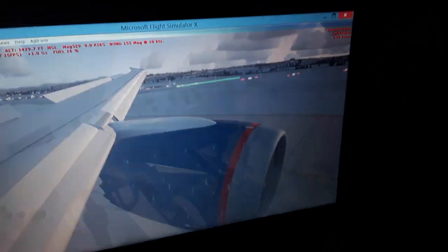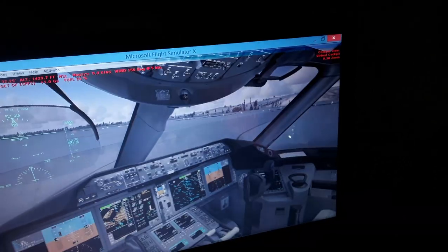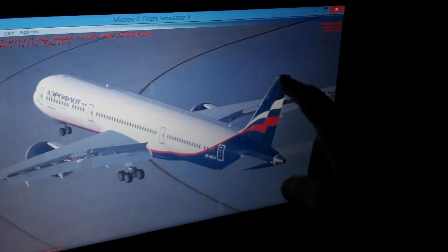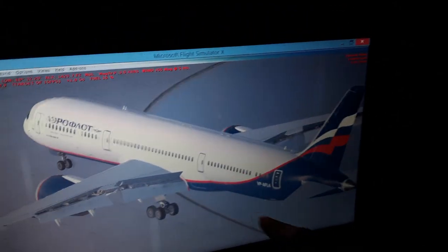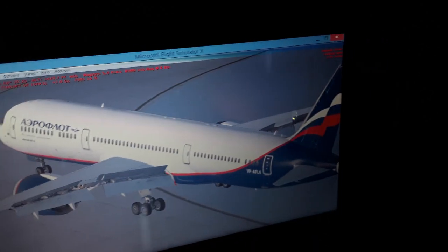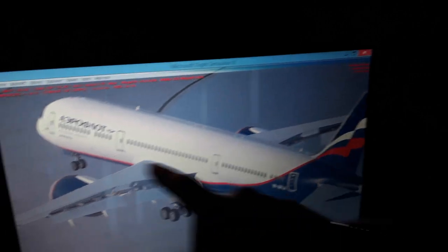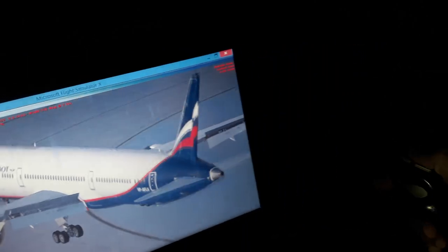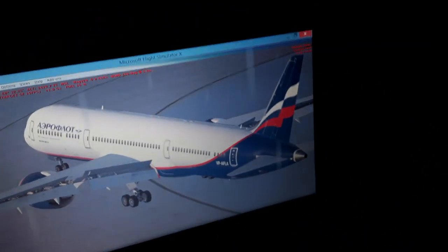So you have the rudder pedals over here to control the rudder, or the nose wheel together with the rudder on the ground. Also, when you land the aircraft, you first use the rudder at around 250 kilometers airspeed. Then as you slow down and touch all the wheels down, below a certain airspeed, the nose wheel becomes activated from the computer again. You don't need to do anything for that. The computer of the aircraft does it.